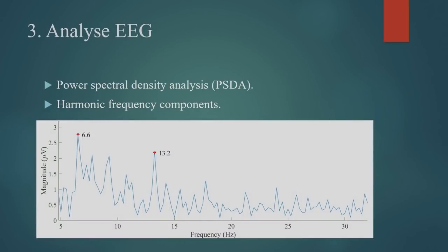Now, in the earlier slide, you saw SSVEP exploits frequency domain characteristics in brainwaves. So the most straightforward way of analyzing SSVEP would be a simple power spectral density analysis. But unfortunately, EEG is not similar to audio signals, where you have a very good SNR, very good signal quality, so power spectral density analysis works very well.